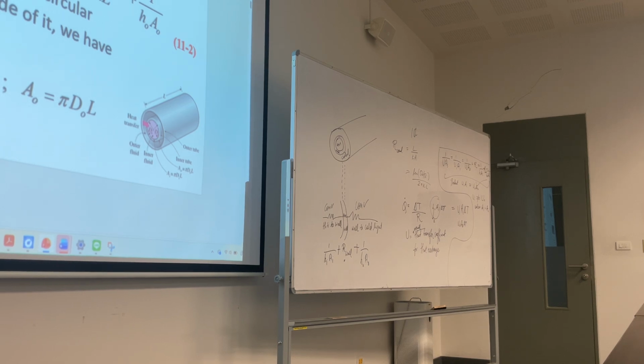Okay. So the same derivation is written here for a double pipe heat exchanger, right? The resistance is this from chapter 3. Ln d naught divided by di 2 pi kn. Okay, and the overall total thermal resistance for a double pipe is again this: convection, then conduction, then convection. Right? This is from chapter 3. Area AI is inside, so we are using di. AO is area outside, so we are using DO. DO is diameter of the outside pipe. DI is the diameter of inside pipe.